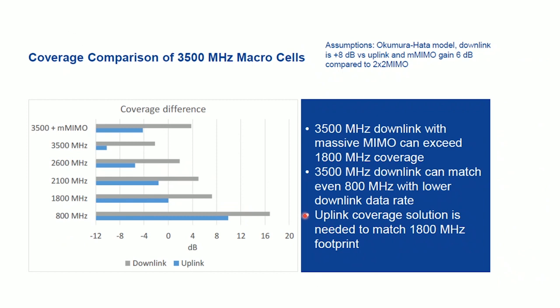So 5G benefits more than 4G and more than 3G from having a low noise, low interference uplink. This means that both PIM and thermal noise must be minimized in 5G to provide a decent UE battery lifetime.